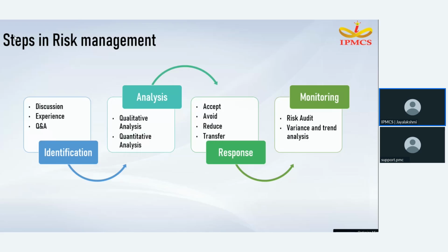The main steps in risk management: the first one is risk identification. We can identify the risk by discussing it with different people, such as team members, laborers, or the local people around. This discussion will help us, as the experienced people inside the team can bring up risks that they identified out of their experience. When we discuss it with the local people, we could identify the nature of the land around the site, and also the nature of the climate or weather at this site.